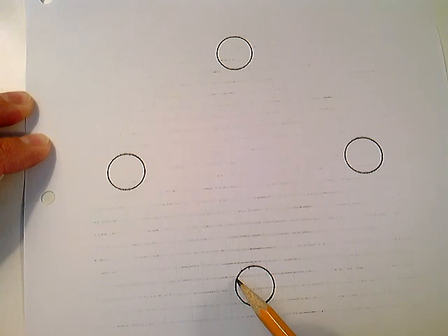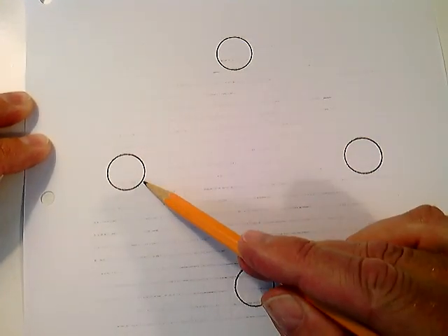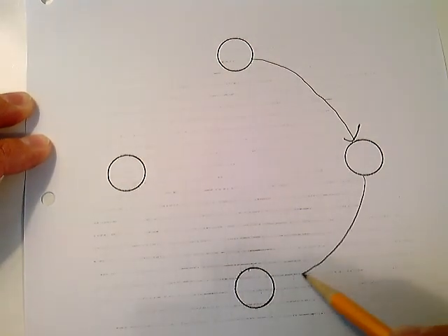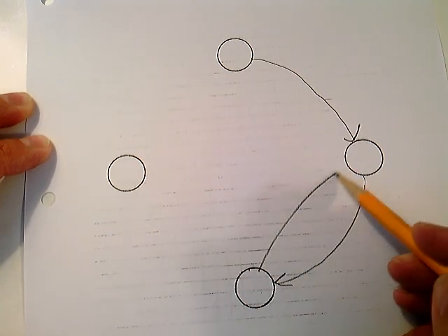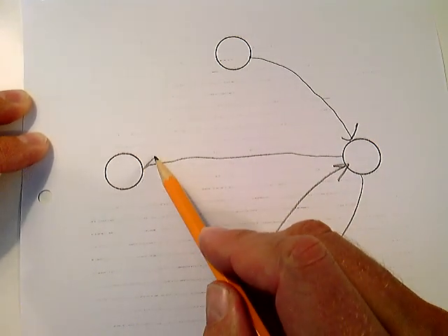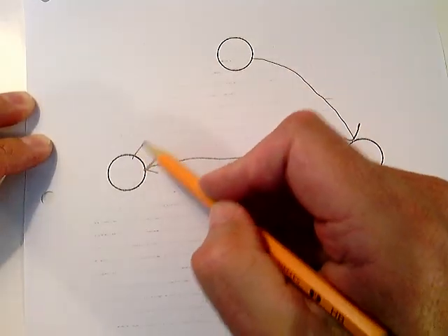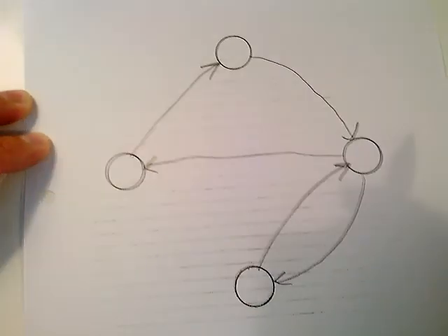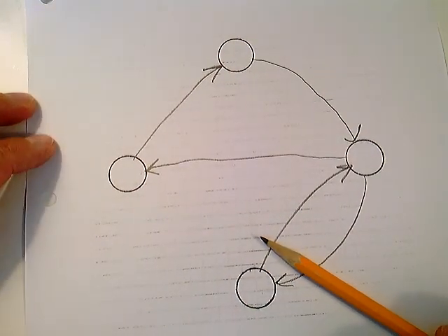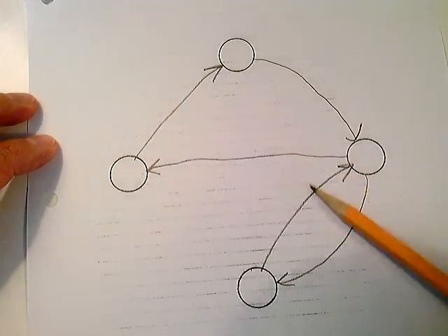You're not going to have an arrow gone from wash to wax. You're going to have an arrow gone from here to here to wash. You're going to come back here to rinse. And then when you get to state 6, guess what? You're going to come over here to wax. Then you're going to come back here. You have to complete this state transition diagram and hand it in to show every possibility in this automatic car wash. I just got you started here.